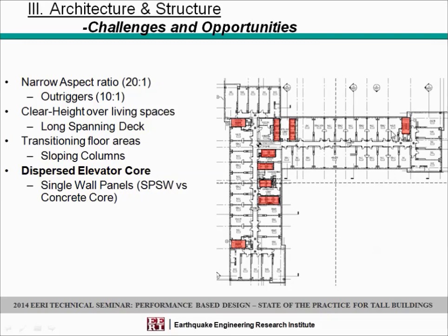We ended up with an elevator core all the way on the right side, a middle core, a distributed core here for different aspects, stair exiting. And we took the original concept, we showed them if you do concrete, here is what your distribution of walls is going to be because of the different heights of the different wings.